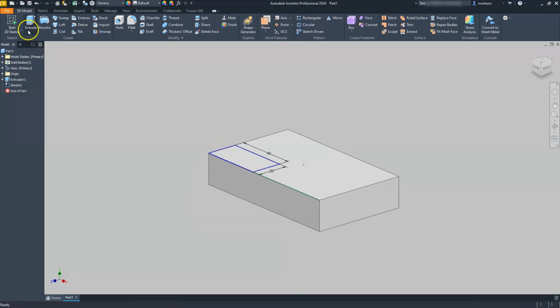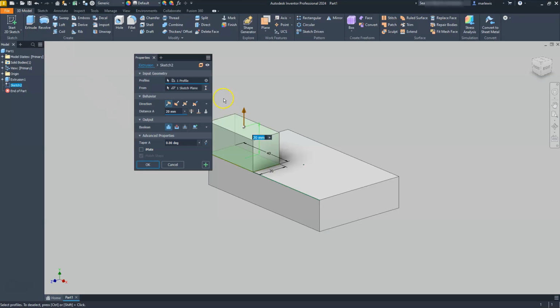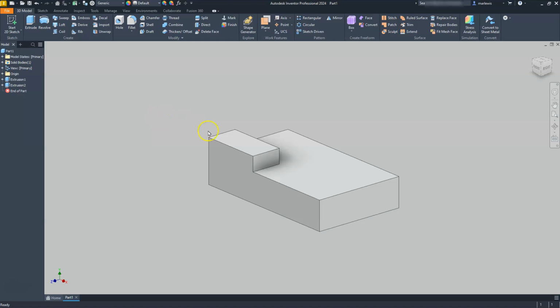Next thing I'm going to do is use the extrude command. And then I need to send this up a height. The height that I'm going to use in this case will be 10. Okay, now I can place my circles or my holes onto this, and remember these are two same size holes, so I'm going to use a sketch as opposed to using just directly the hole command. So I'm going to select this top surface.